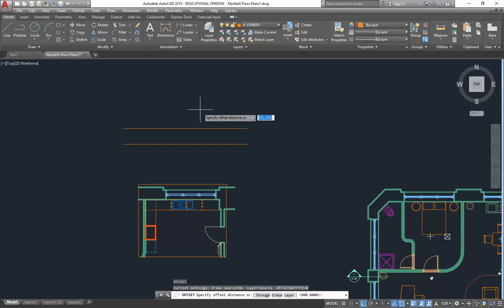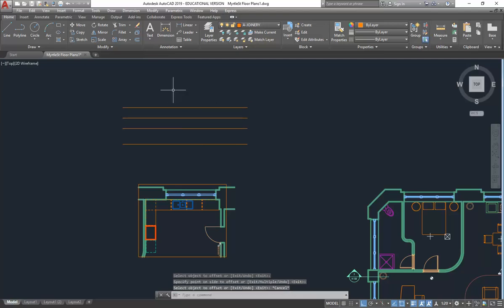So we've got 900 for the bench top, and then if you come up another 600, that's the height your cabinet should be above that. And so that gives you 1500. And then again, it's another 600 high for the units themselves. Okay, that takes you to 2100. And that's pretty standard, even though some people who aren't as tall like them to be a bit lower, but you shouldn't do that. Yeah. So the high shelf is still going to be half of that, so it'll be 1800, which is just doable. So yeah, that's a good starting point, and then you project your lines off.